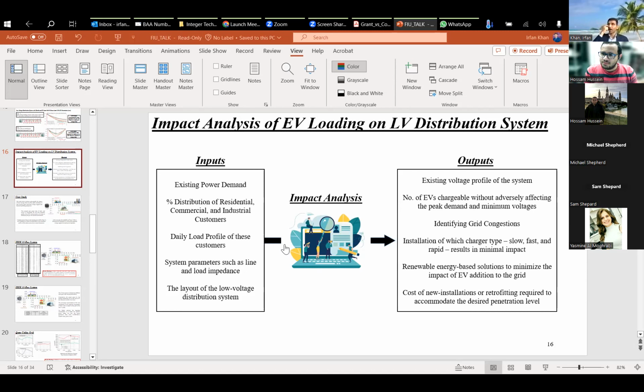We simply did not divide all the buses and subsystems we assumed for the marine system into these three subloads. What we did was divide the entire system into three subzones, or three subsystems, but we did not divide further. Marine was only shown to see the impact of distributed filtering in the case of harmonics, but we did not divide that into different types of load. That was used only for the utility grid, the Qatar grid.